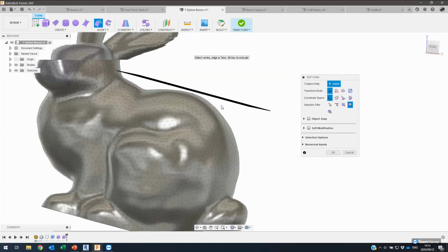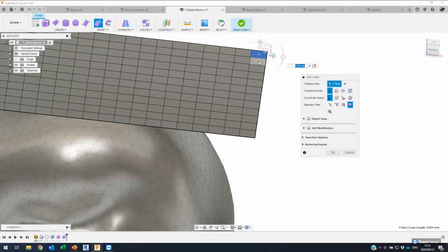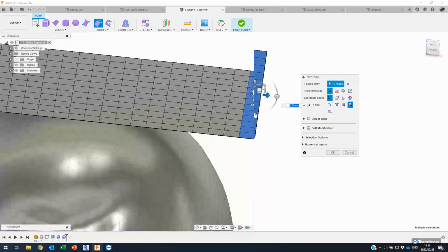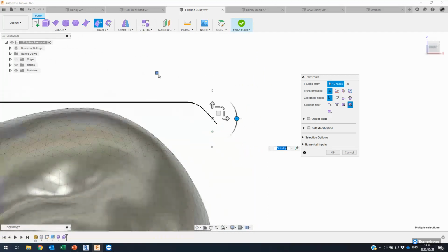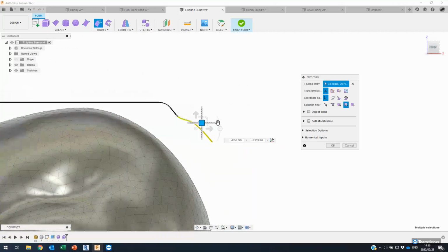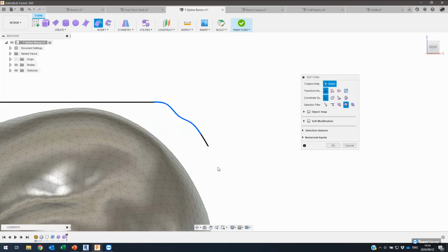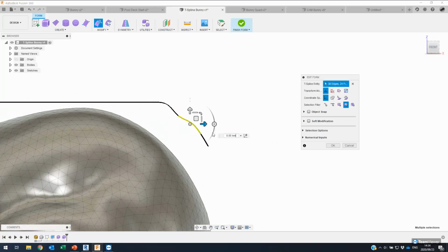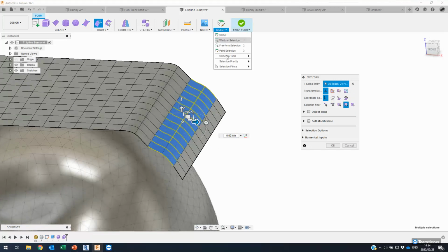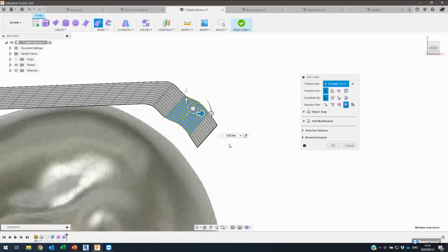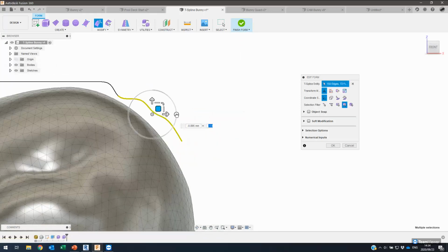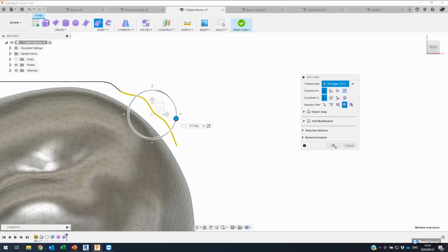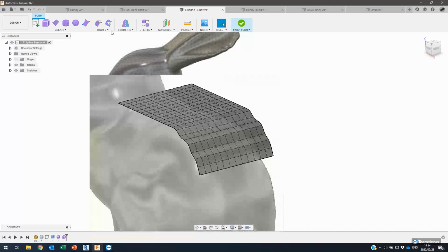It looks fine, and you can go ahead and do some modification, match it a lot closer to the shape, to the mesh itself, and that does aid in pulling it to the mesh. Just want to change my selection type here. And the closer you get it matching to the mesh before you actually do the pull, the better it is. However, it doesn't need to be perfect.